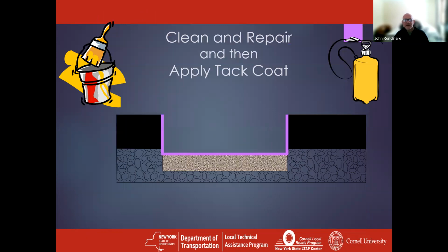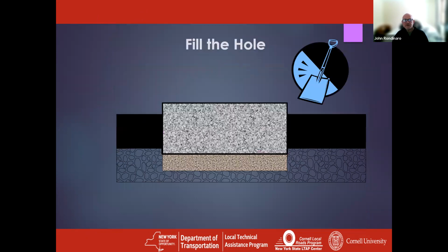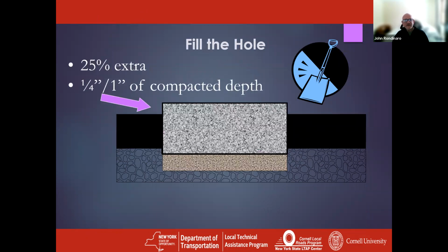Clean and repair, and then apply your tack coat. Tack coat is critical, just like in any paving operation. Fill your hole 1/4 of an inch for every inch of compacted depth.